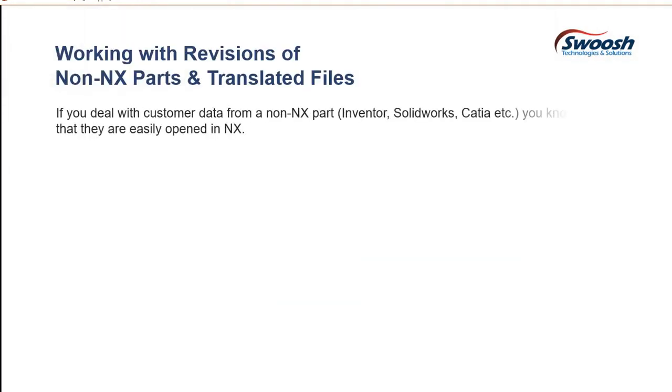So we all know that for working with that non-NX data, it's very easy to open. You just say File Open. There's a filter in the Open dialog. You can pick Inventor, Solidworks, Catia, Parasolid. You can pick IGES files, lots of file types there you can pick and open. You'll work with them, create drawings, add dimensions. In manufacturing, you run toolpaths on the faces and edges.